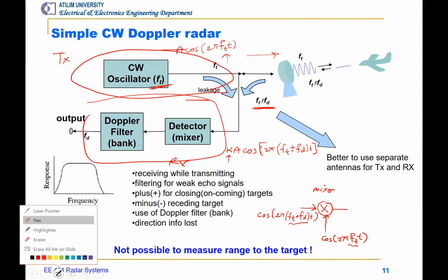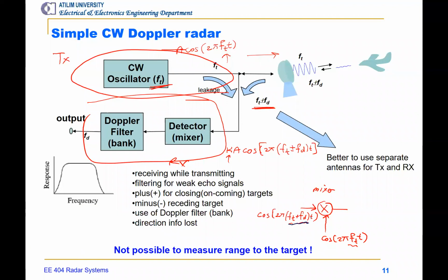As you might remember from the laboratory, if this is frequency A and this is frequency B, let's say, the frequency of the output signal is going to be n times Fa plus minus m times Fb. All the multiples of these frequencies appear at the output of the mixer, and we usually use a low-pass filter. So we connect a low-pass filter here.